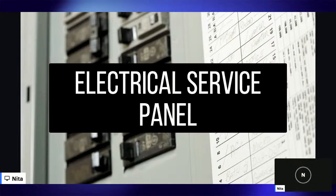So again, our service equipment is essentially the main disconnect point for all of the power to the house. We call these main disconnect, main breaker, service disconnect. If you have fuses, switches, circuit breakers, circuit breakers are most common, but these are all considered to be service equipment. Your power must be able to be disconnected with no more than 6 touches of your breakers.